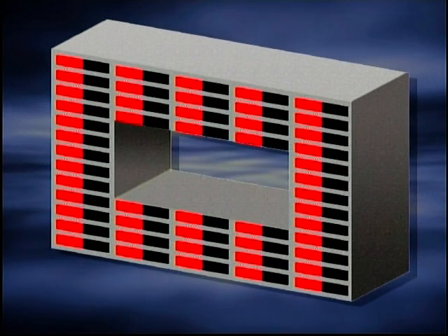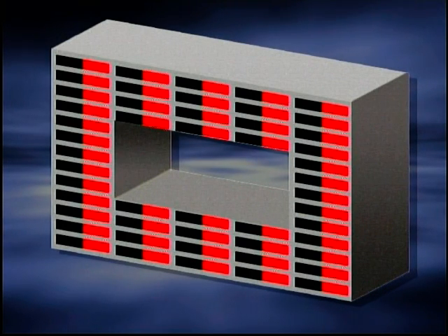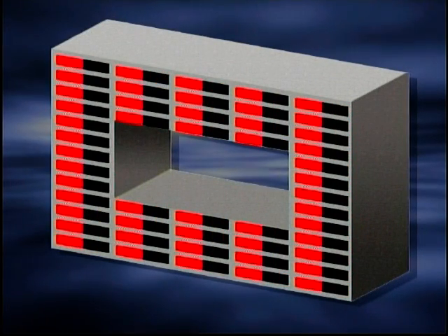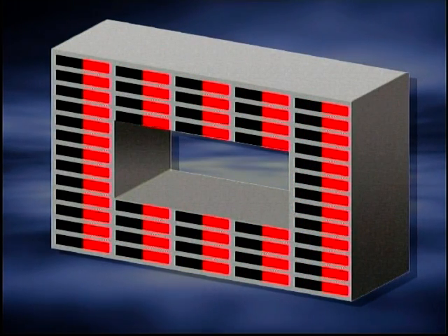Another core loss is called hysteresis. This loss is caused by the reversing of the magnetic polarity of the atoms of the core material. The polarity of the atoms is indicated by the colors at each end. Each time the current reverses in the primary winding, the atoms of the core must also reverse their polarity, and frictional loss is developed.